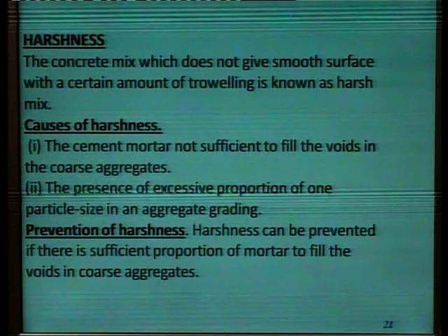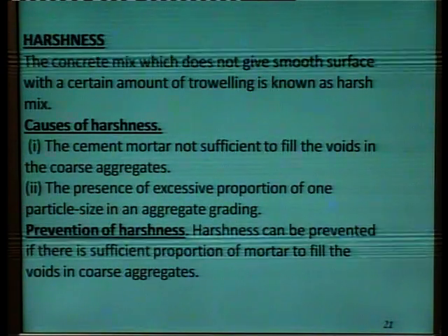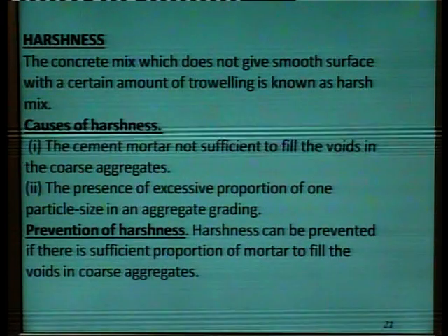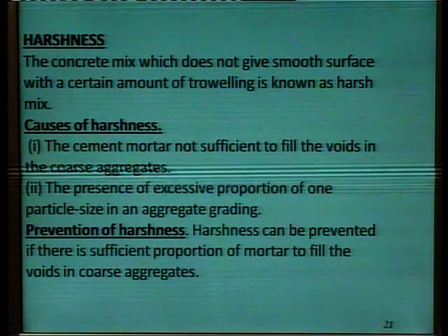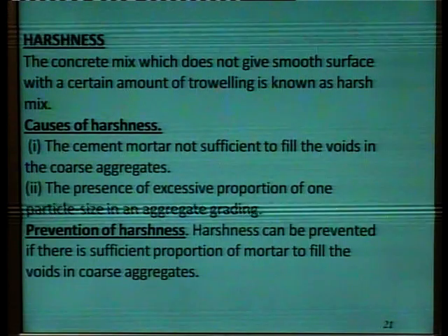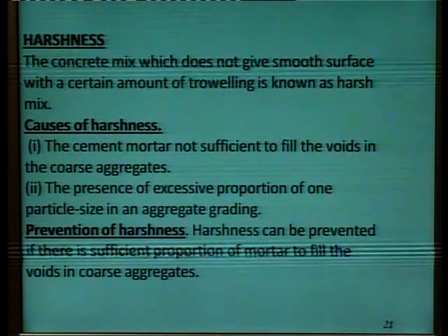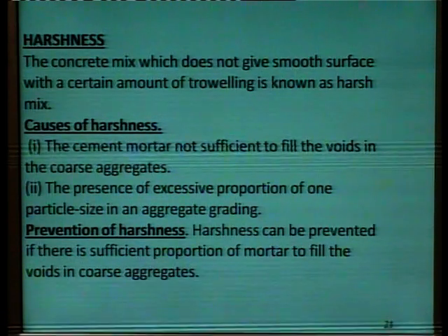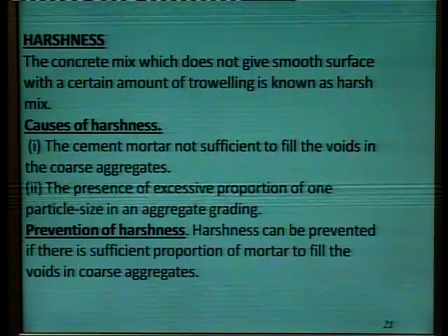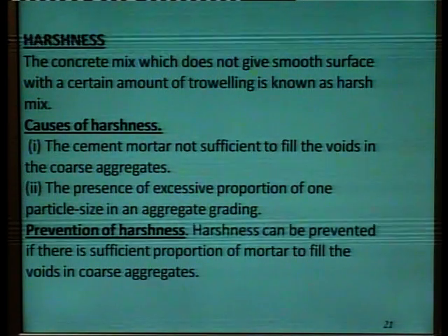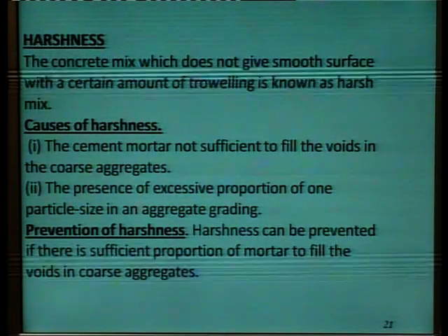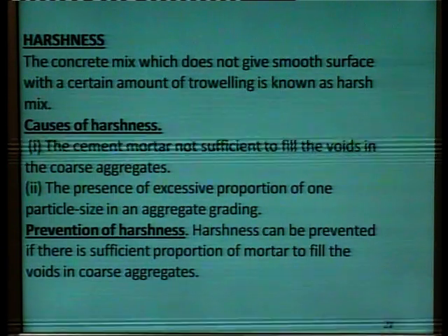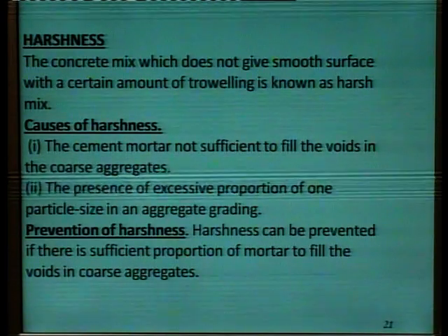So, these are the two causes for harshness. Prevention of harshness. Harshness can be prevented if there is sufficient proportion of mortar to fill the voids in coarse aggregates.